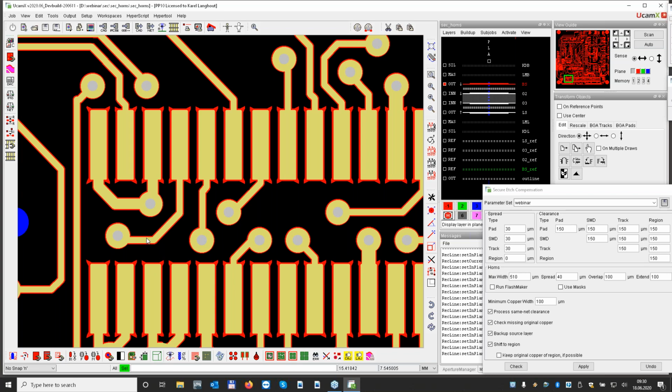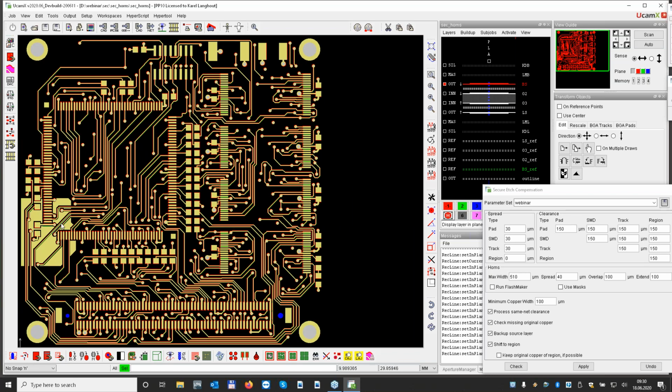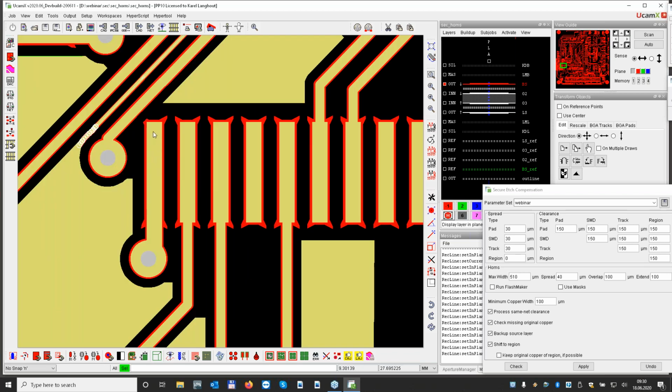Also, like we said in the presentation, where the clearance would not be enough, we shave away the horns. And like I explained before, this is not a big thing because over here it's very dense, so the corner will not be etched that much as other corners over here, where the etching will be more. So in the end, your image will look very fine.